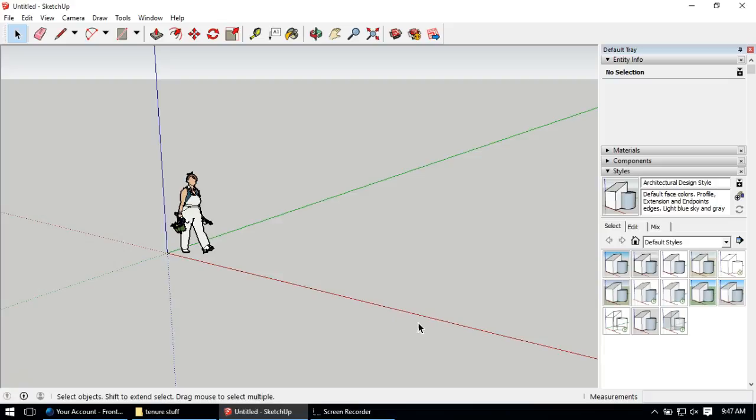So with that, what we're going to do is SketchUp always opens. This is our drawing field, right? We'll go over that in class. And this is our axis. It's like X, Y, and Z is the blue. And SketchUp always has this funny little person in there. It changes per version, just gives you a scale figure, and that's just an object in here. So I'm going to go to my black arrow, click on this person, and hit delete. Get a blank drawing screen.